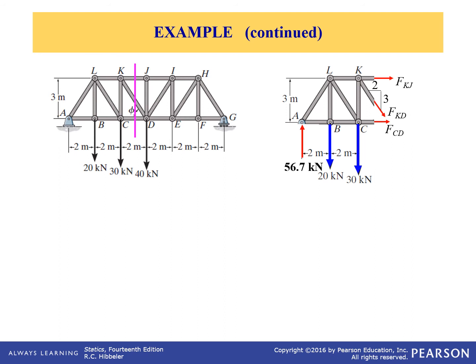We can do a moment equation, a sum of the forces in the X, and a sum of the forces in the Y. What you want to try to do usually first, and I've done these problems, and I'll try to remember when I do some examples for this chapter to do one of these, is you can do all moment equations and actually knock things out, because moment equations will knock things out if the forces are going through the point. So the author starts this problem by finding the moment at point D. And you might say, hey, professor, point D is not on the picture anymore.